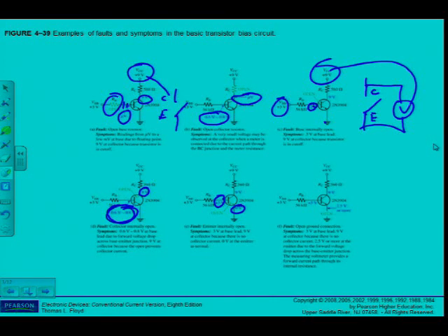In other words, the base emitter voltage should have been approximately 0.7 volts. But I do get 3 volts, and the track seems to be fine up to the base. But it means that the emitter then is internally open. I still have the 9 volts there, so it means that the transistor still is in cutoff. I still measure VCC between collector and emitter.